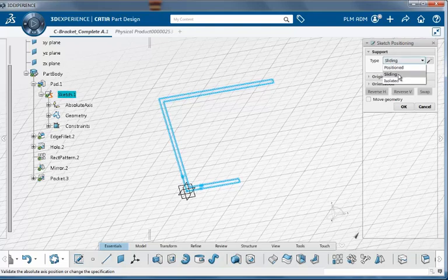And finally, the isolated sketch breaks all axes links, such as origin and orientation, with the three-dimensional position. Only the three-dimensional position is kept so that the sketch does not move. Also, you can't define the sketch support, origin, and orientation with this isolated option.